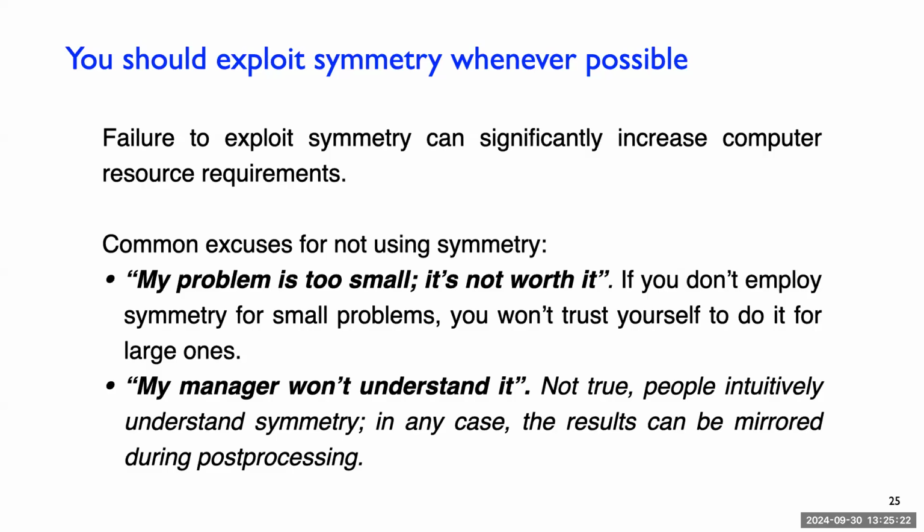So I would suggest to use symmetry in all cases where it's relevant. And then my manager won't understand it. So that's not true. People understand symmetry. It's not that complex a topic. In any case, Abaqus and other software can mirror your results.